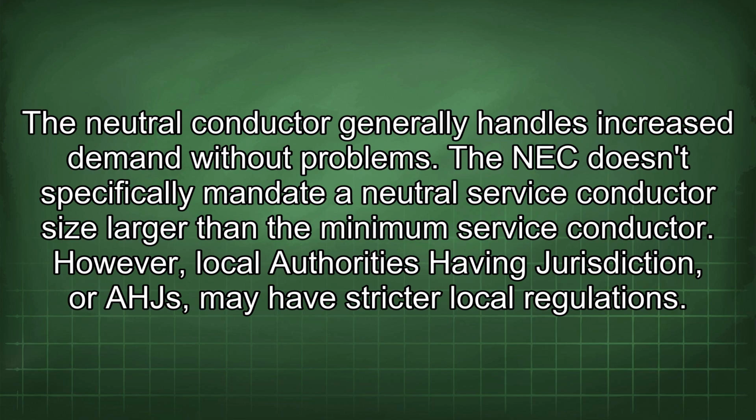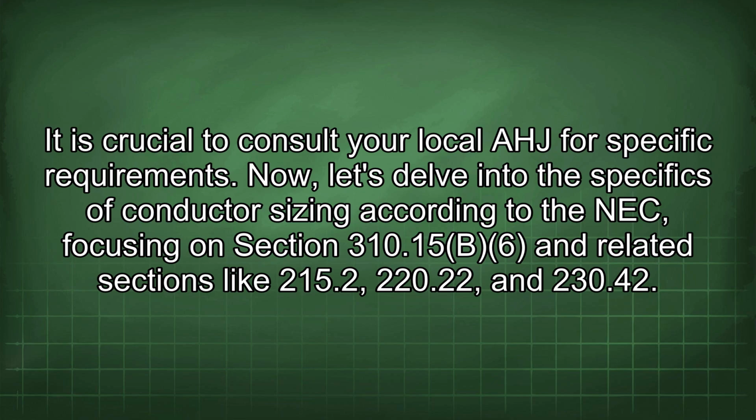The NEC doesn't specifically mandate a neutral service conductor size larger than the minimum service conductor. However, local authorities having jurisdiction, or AHJs, may have stricter local regulations. It is crucial to consult your local AHJ for specific requirements.